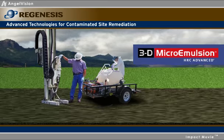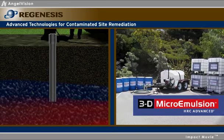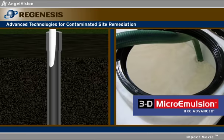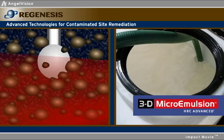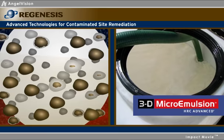3D microemulsion is applied to the subsurface. The material is simply pressure pumped into the contaminated saturated zone. 3D microemulsion moves out into the aquifer until it sorbs onto the aquifer medium.